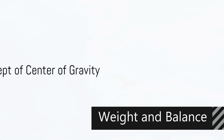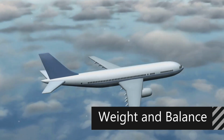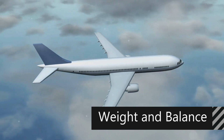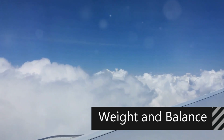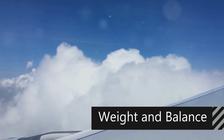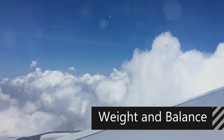CG. What is it? The center of gravity, CG, is considered the null point of action of the various gravitational forces acting on an element with its own mass. The CG is also considered a point of balance. Both lateral and longitudinal balance are important, but the main concern is the location of the CG along the longitudinal axis. Its importance lies in that the stability of the aircraft depends on it.